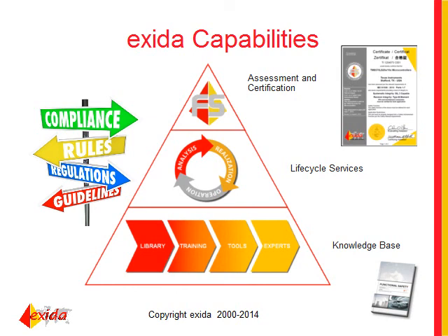And the point's very true that it doesn't address the operator decision. People might say, well, I want SIL 2 at least for my gas detection and annunciation phase. I'm not going to worry about, and that's just a for example, I realize my person has to make the right decision then, but I want this level of reliability for this part of my function.